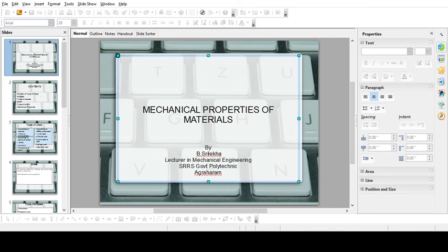Depending upon the temperature, these stresses, even below the elastic limit, can cause some permanent deformation. So creep is a very important property to be considered while designing a component to withstand stress at relatively high temperature. It means the component should withstand the high temperature. It should not simply deform when we are operating it at high temperatures.